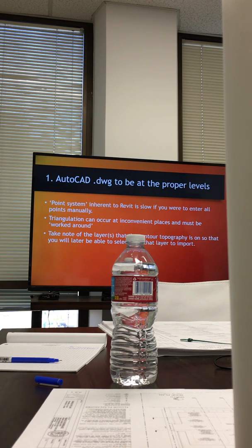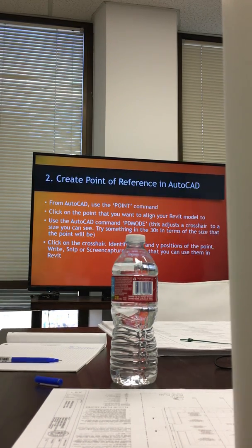The key thing that I found in going through all this is you need to make sure that you note what layers your topography is on, so that you'll be able to only select that layer when you're going into the next phase of using it in Revit. Okay. So next,